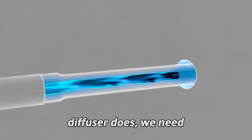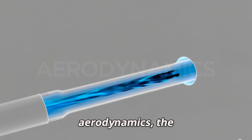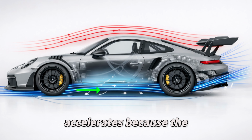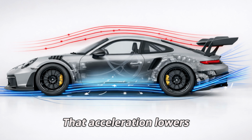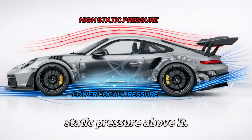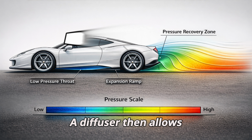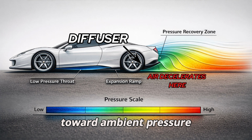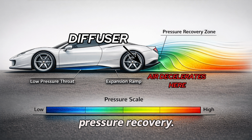To understand what a diffuser does, we need to revisit one of the core ideas of aerodynamics, the relationship between velocity and pressure. Air moving under the car accelerates because the underbody acts like a constricted passage. That acceleration lowers the local pressure under the car compared to the static pressure above it. This pressure difference is what generates downforce. A diffuser allows this fast-moving, low-pressure air to decelerate gradually back toward ambient pressure without causing separation. This process is called pressure recovery.